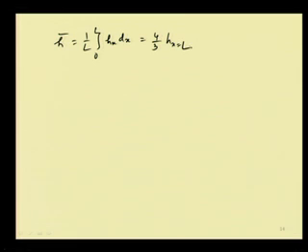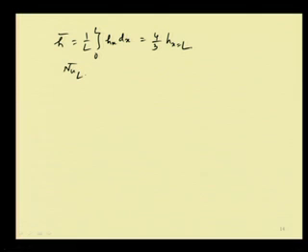Okay. And then we have already done that h bar is equal to 1 by L integral 0 to L h x dx. This is the average heat transfer coefficient, and in this case it is something different: 4 by 3 h at x equal to L. By this way we can find out the average Nusselt number also. We can find the average Nusselt number based on L, equal to h bar based on L, at x equal to L, into L by k. So, we put the expression for h bar at x equal to L, and we will get the expression for the average Nusselt number.